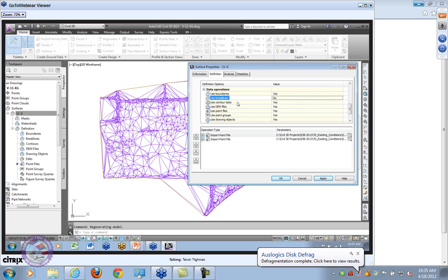I can put in stuff from the USGS's contour data, and say, no, please don't use that now on my surface, and still look at what my surveyors did, what my aerial people did, without any of that stuff getting in the way. So this is a way of, again, analyzing the data. And I employ both the build operation and my style to do that.